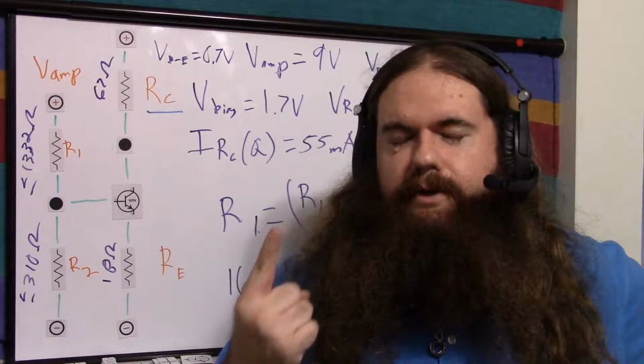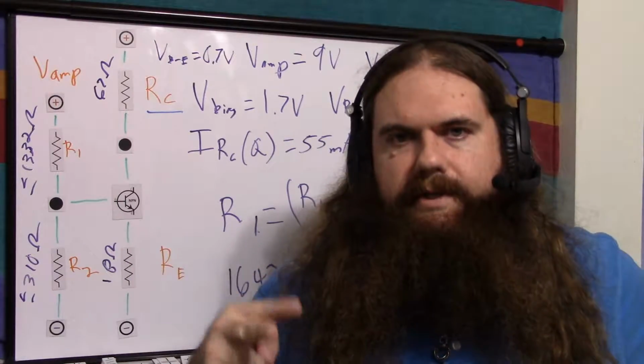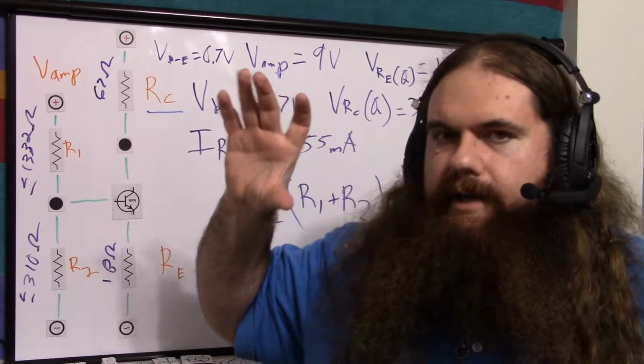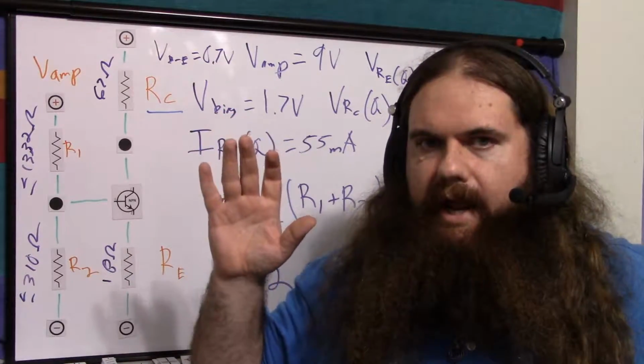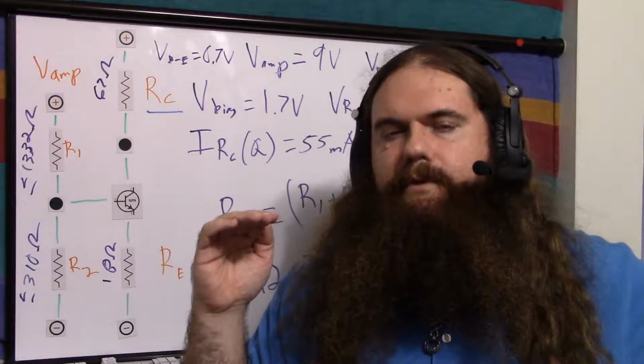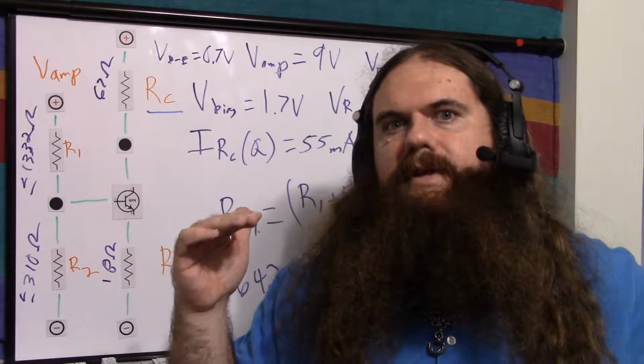Because you're basing the current on your power target and you're basing your resistance on that. You're actually saying, this is how much voltage headroom I have. I want to get in the middle of that voltage. How much current gets me in the middle of that voltage?